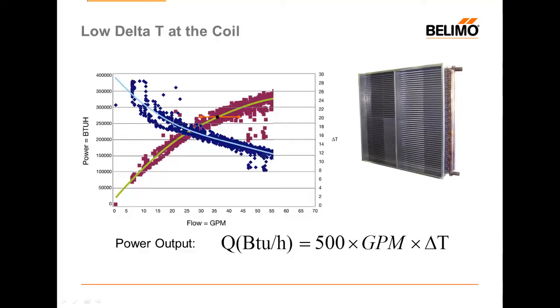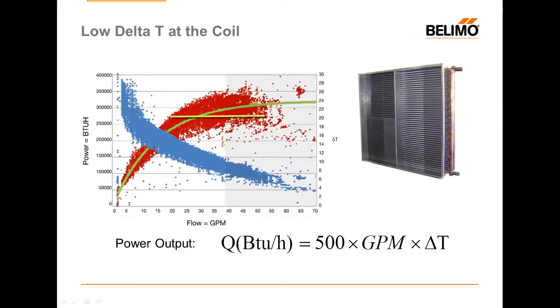However, if we continue pumping water, this is what happens. My coil curve is now completely flattened out, and I'm no longer producing BTUs. The only thing that happens if I increase flow now is that I reduce my overall delta T. This curve has a certain degree of thickness to it, but imagine how many different flow rates we could create the same load if we had a curve that looked something like this.